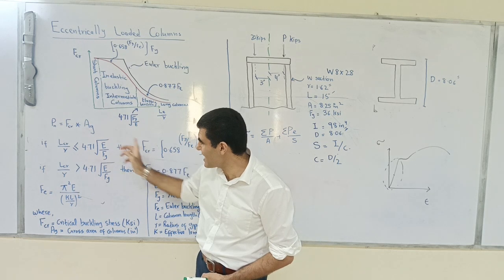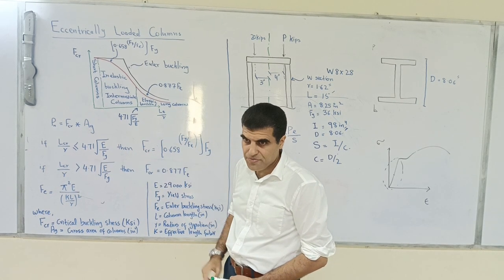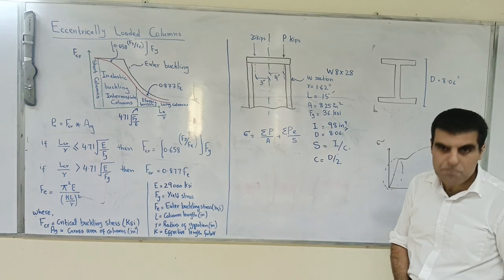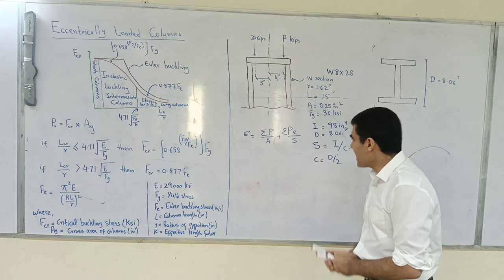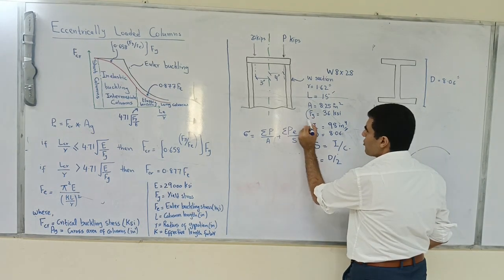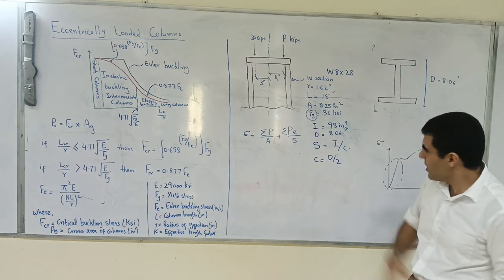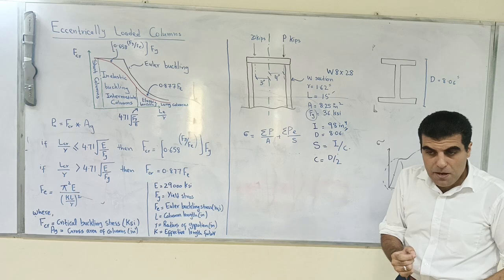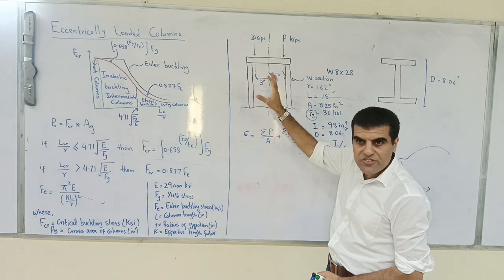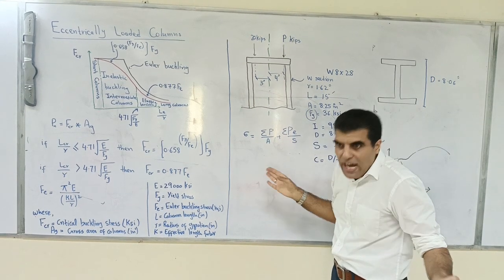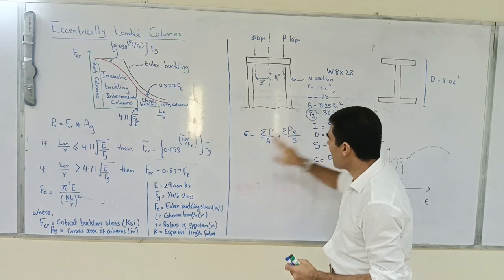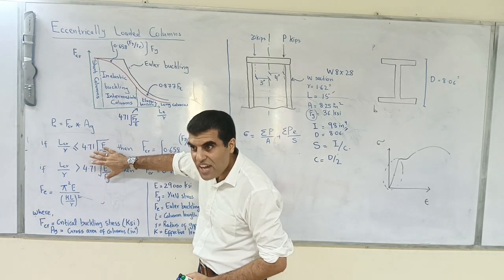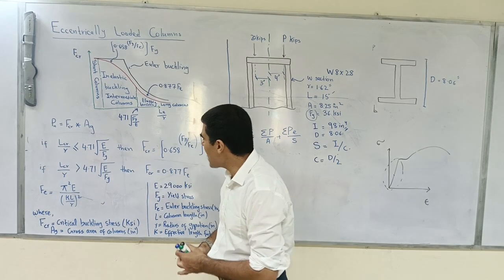We have to find out what the critical stress is. Okay, once we find out that critical stress, we can plug it in here and we can find out our P. Okay, so my point is that although Fy is known to us, we can just close our eyes, put this Fy over here, find out the unknown P. We can do that. But that method assumes that your column is failing only in compression. But we don't know that. So therefore, we can't use stress is equal to Fy. We have to find out this stress from here. Okay? What is our critical stress?